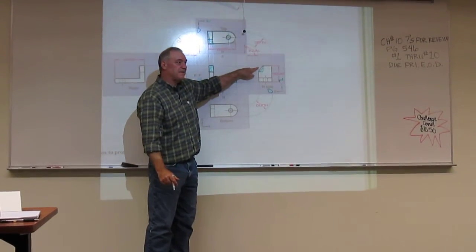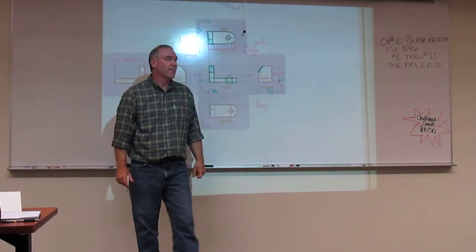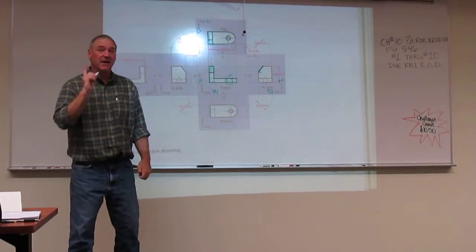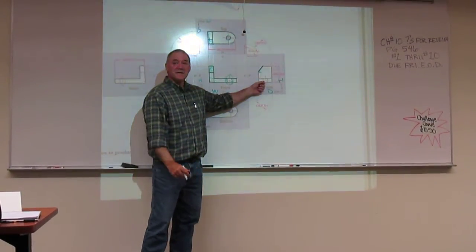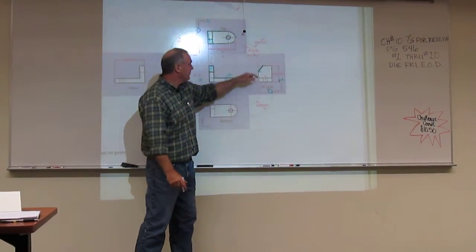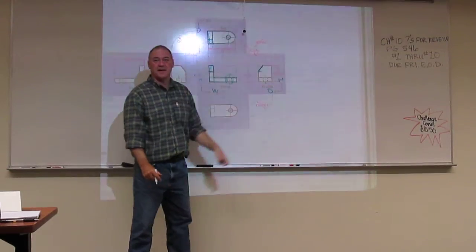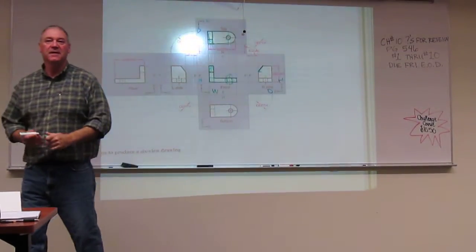I have to provide this view only for one line. But I've got to give it. This is a 3-view drawing. These two views describe every piece of geometry except for that edge. And I'm going to give them a right side view to define that. And then it's a done deal.